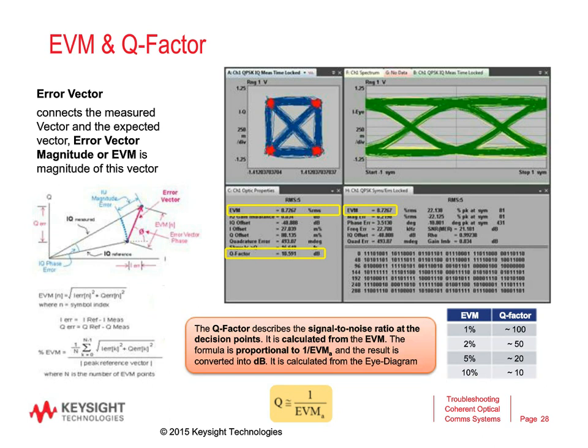And then the difference between these two vectors is considered to be the error vector. For our measurements here, we are concentrating on the magnitude of that error vector, and we call it the error vector magnitude. It is more or less a figure of merit and gives you a first indication if you have a rather good or more or less a bad signal on your transmitter.